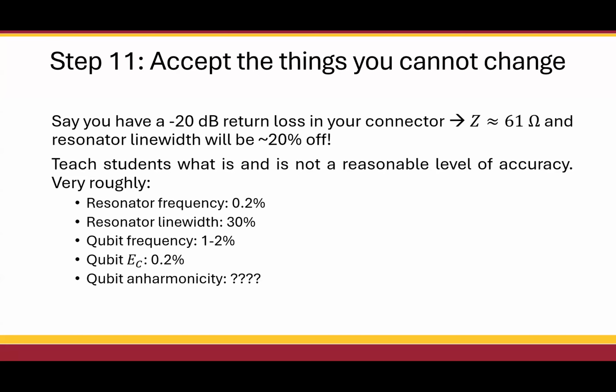Likewise, resonator frequency, you should be able to hit that really, really well, but you might have biases. That's the thing. You're going to be repeatable, but not accurate if you're not careful, because it's hard to correctly include things like crossover junction or air bridge crossovers, to really account for the effects of flip chip. I'm anxious to hear what Ben has to say about that later. But it should be repeatable.